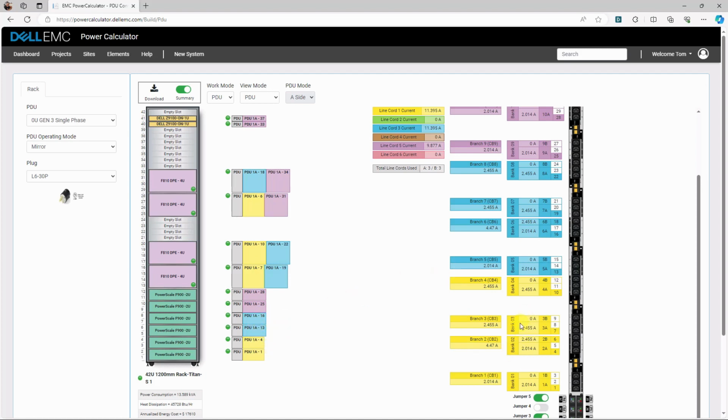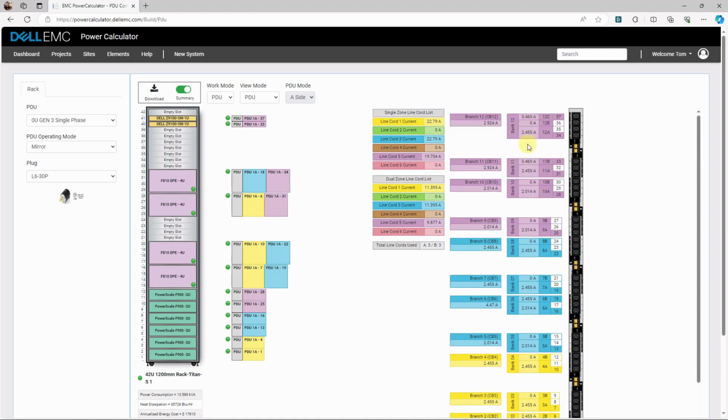And if we were to lose a breaker, so this guy down here, this branch has two people plugged in. This guy has two plugged in, and this guy has a couple plugged in. So now you can see how many amps we're pulling here. So this plug here is pulling 2.4 amps. The switch is only pulling half an amp, but this entire branch or circuit breaker is pulling 2.94, right? And then the same thing for this circuit breaker or branch, 2.94. This branch or circuit breaker, 2 amps. So there's 3 circuit breakers to this one cord.